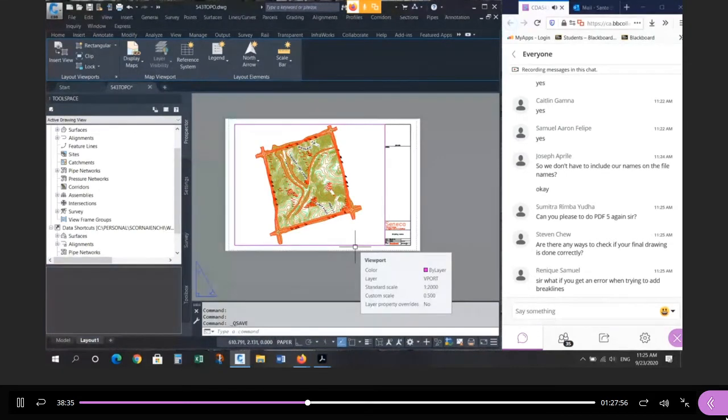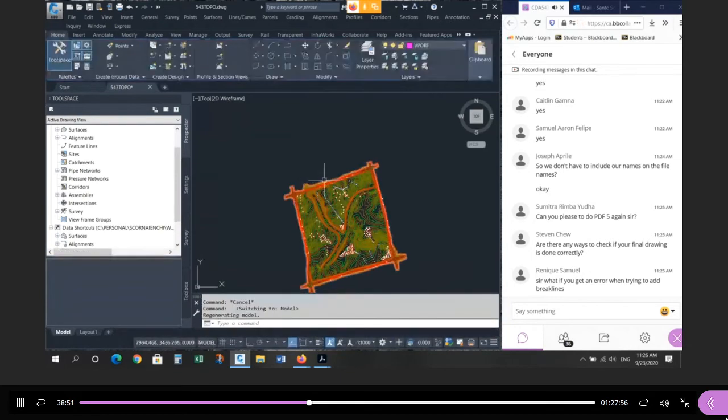When you create the break lines, or define the break lines for the surface, you're going to get some errors. You can just ignore them. It's telling you that there are some lines that cross each other. Don't worry about it because you're using the proximity function. The errors don't matter. They're not going to cause a problem. Let me show you. I think I can duplicate that.